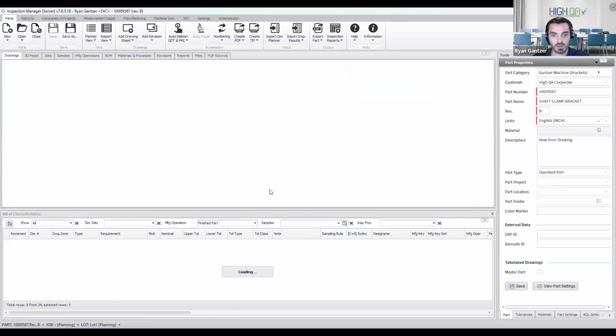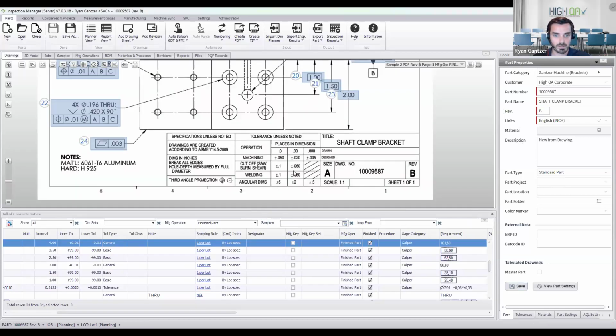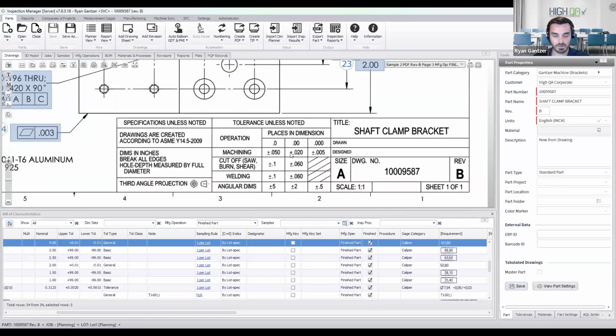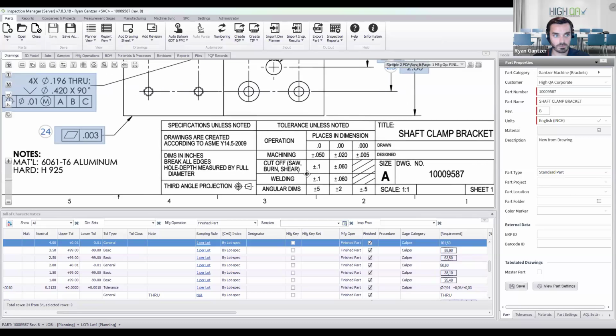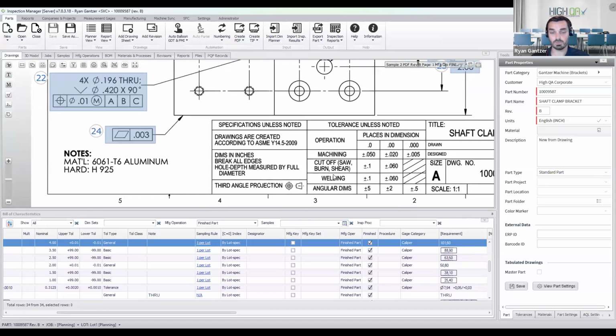All right, so we talked about the tolerancing, right, where that comes from. Next, for those of you that have a need to balloon notes, we're not going to auto balloon notes. Similarly, there's just not enough standard to do so. Some people want it, some people don't. It can be anywhere on the page. But another efficiency tool we have, top left of the screen, is this T icon to balloon notes.